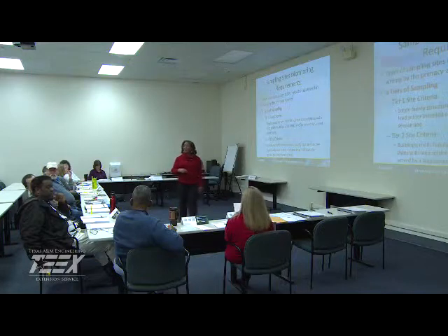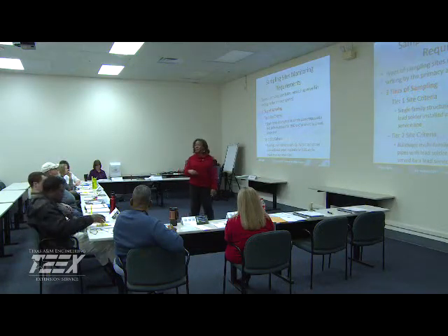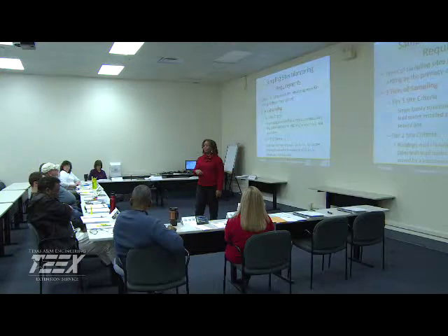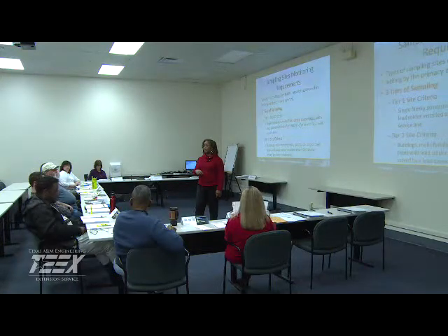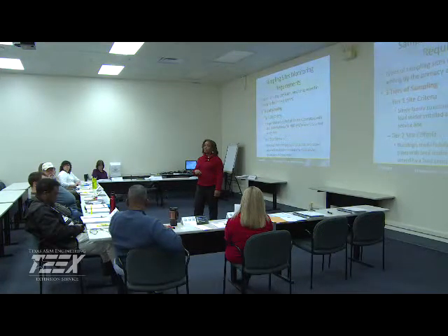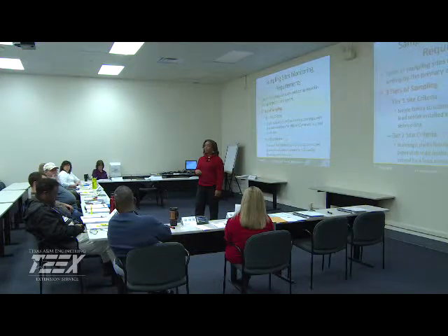You target the tier 1 sites. You try to identify all of those. If you don't have tier 1, then you move to tier 2. Now, tier 1, the single family detached structures prior to 82, a lot of them were built with copper. The issue here in Delaware is a lot of homes do not use copper because we have very corrosive water. They use PVC. But they still may have brass fixtures that would have lead in it as part of the brass that leaches out. That's where we look at it.